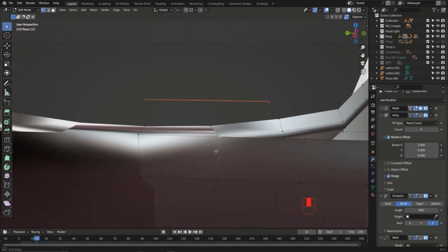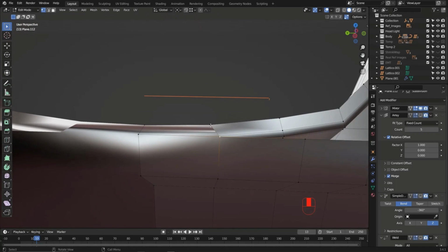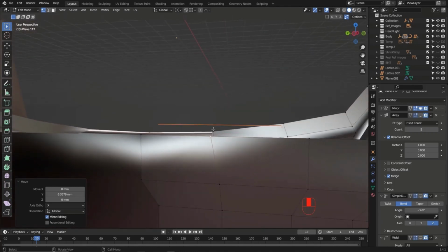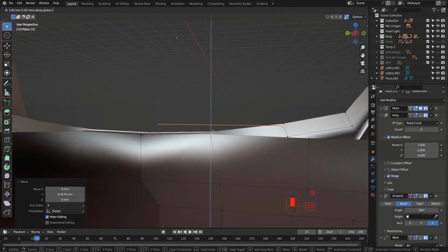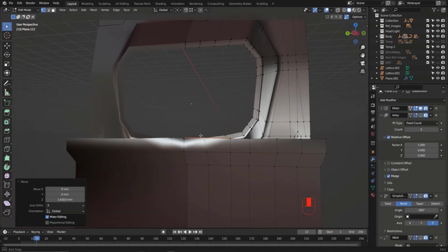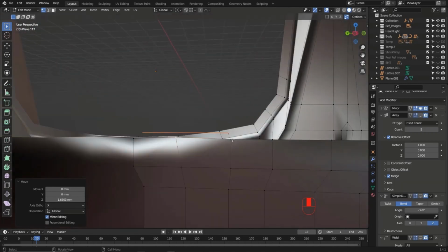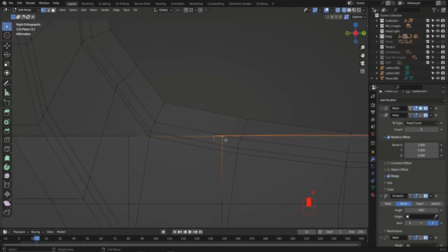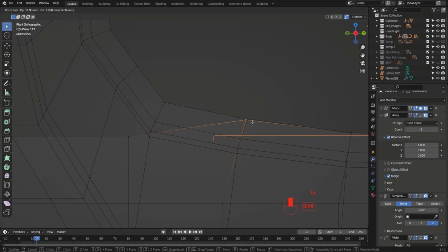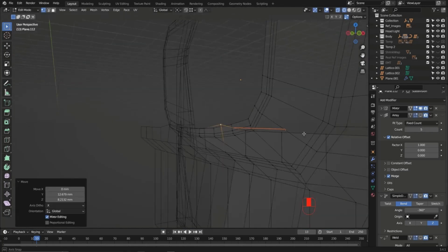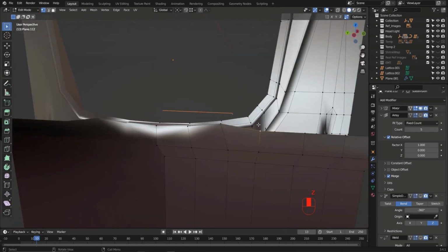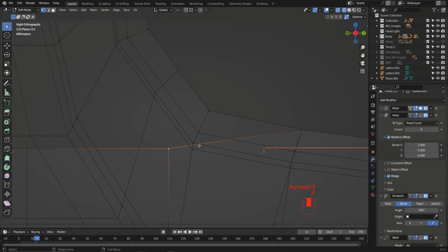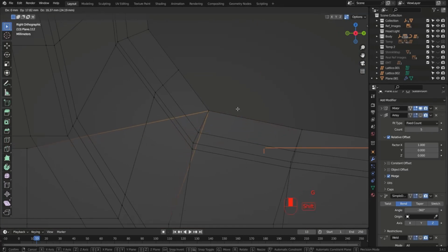And I guess you can align this to this vertex, to the Y direction, G to the Y, hold control and snap it right here. And G to the Z, hold control and snap it. You can go to the right view to achieve that. In the wireframe mode, select the vertex. And let's move this vertex, for example, right here. And this one, the same thing, go to the right, grab it, go to wireframe, and let's put this, for example, right here.